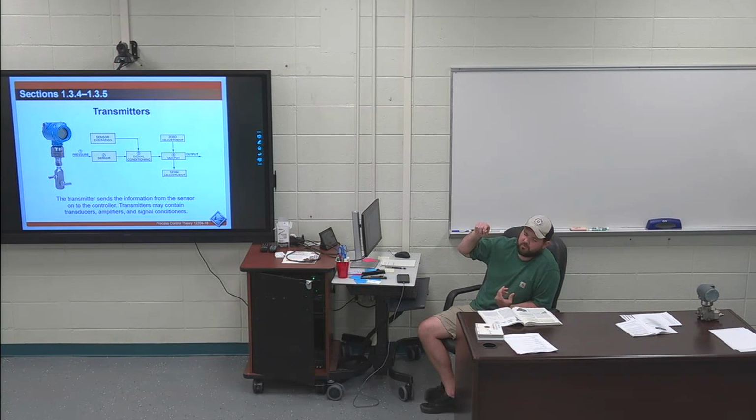You're sending that control valve a 4 to 20 milliamp signal, and that's turning that into a 3 to 15 PSI in order to close that valve. So an I to P transducer is going to be your most common. You're going to need to highlight table 2. You're going to have a question come out of table 2 on the module review all the way at the end.